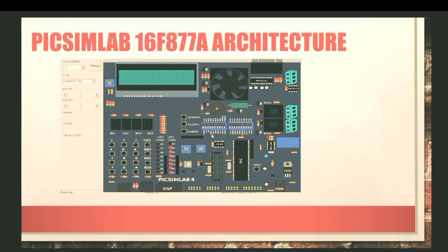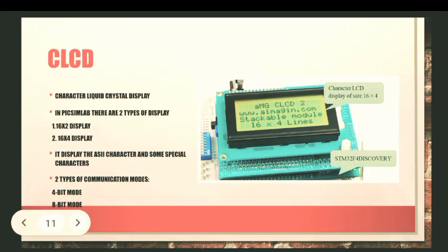A maskable interrupt can be turned on or off by the main processing, but a non-maskable hardware interrupt cannot be turned on and off by the main processing. Examples are TRAP and RST 7.5 or RST 6.5 in the 8085 microprocessor and 8051 microcontroller, while software interrupts include the set flag or overflow flag, etc. An ISR is a software routine that hardware invokes in response to an interrupt.